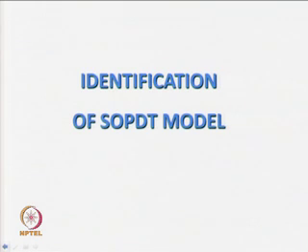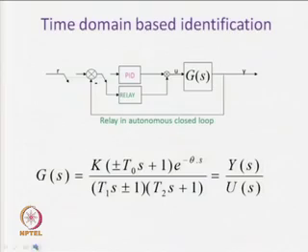The poles can also be right half poles. So, we will first see the structure of the relay test we shall employ for obtaining sustained oscillatory output. Now, the PID controller will be detached first, and a relay will be connected to induce sustained oscillatory output. The relay in autonomous closed loop shall induce sustained oscillatory output.